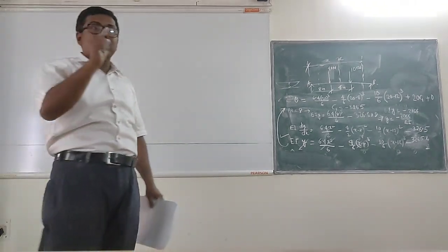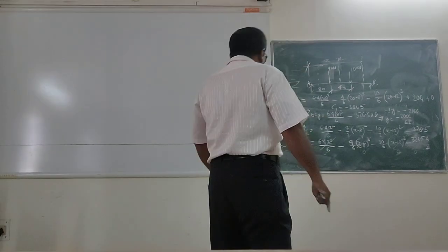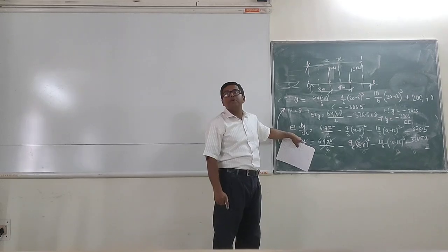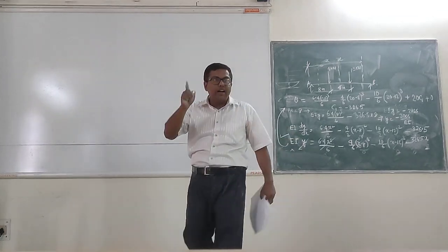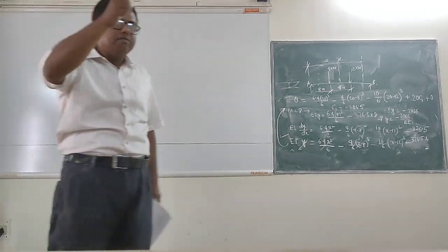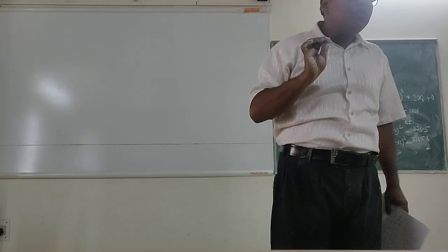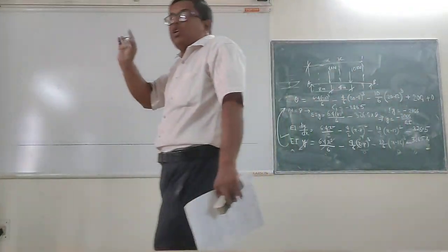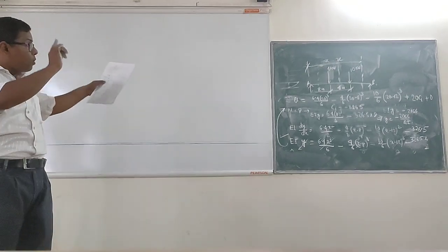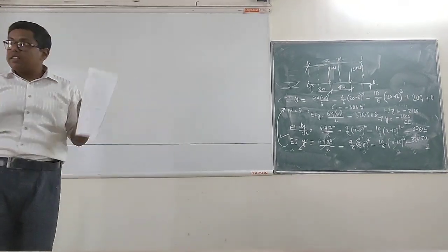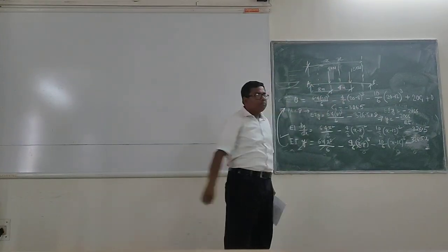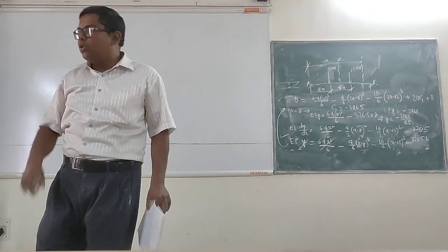So I can make this equation very effective through this. What is slope? Slope is dy dx. So wherever dy dx becomes equal to 0, at that point the deflection will be maximum. Have you understood? Now from this problem, you can see that the deflection will obviously be maximum between the 4 kN and 10 kN loads, because it cannot be beyond the 10 kN load.